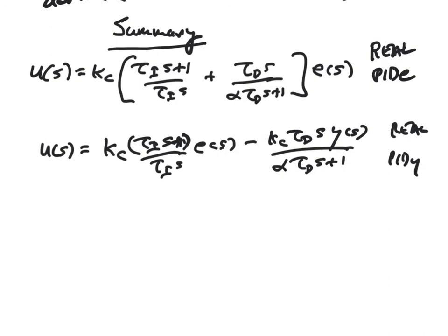To summarize, then, we've developed the top expression in the Laplace domain for real PID, where again we're taking the derivative of a filtered error signal. And the second expression is what we use for a real PID, where we're taking the derivative of a filtered output signal. Hence I call that PID Y versus the top one a real PID E.